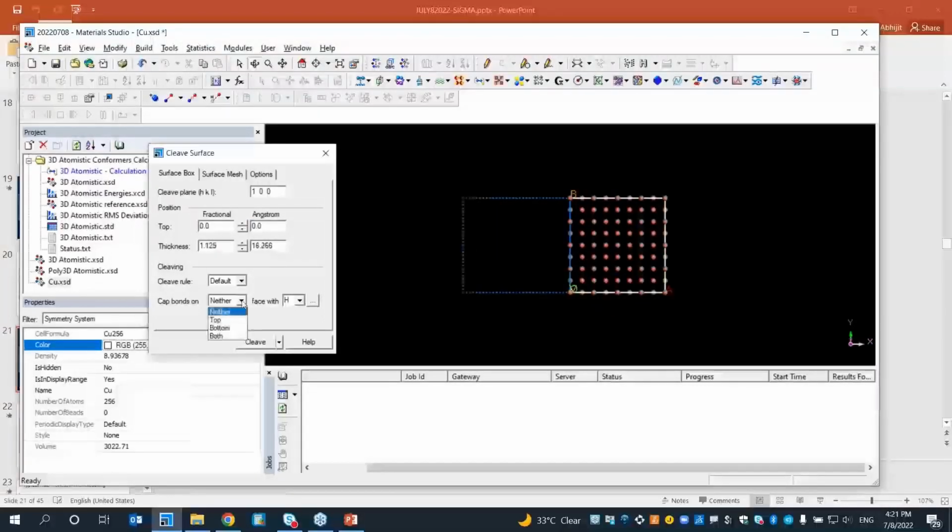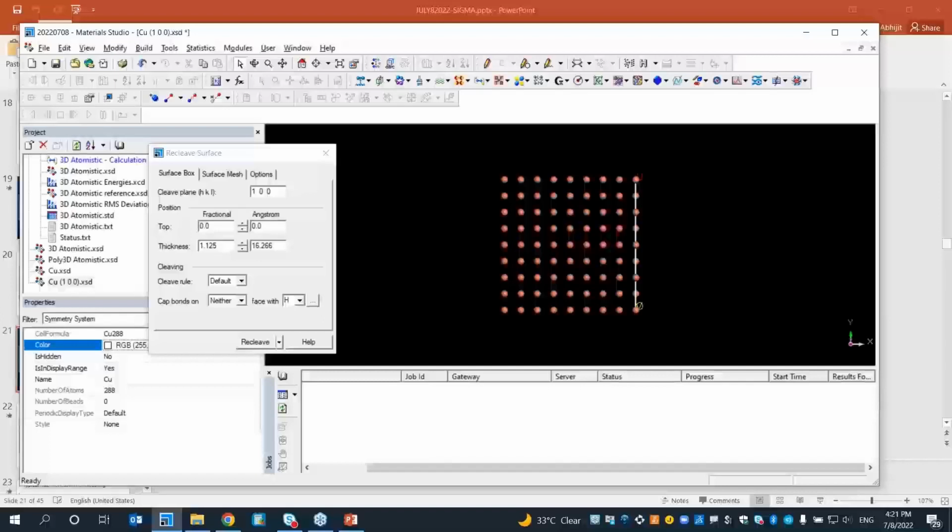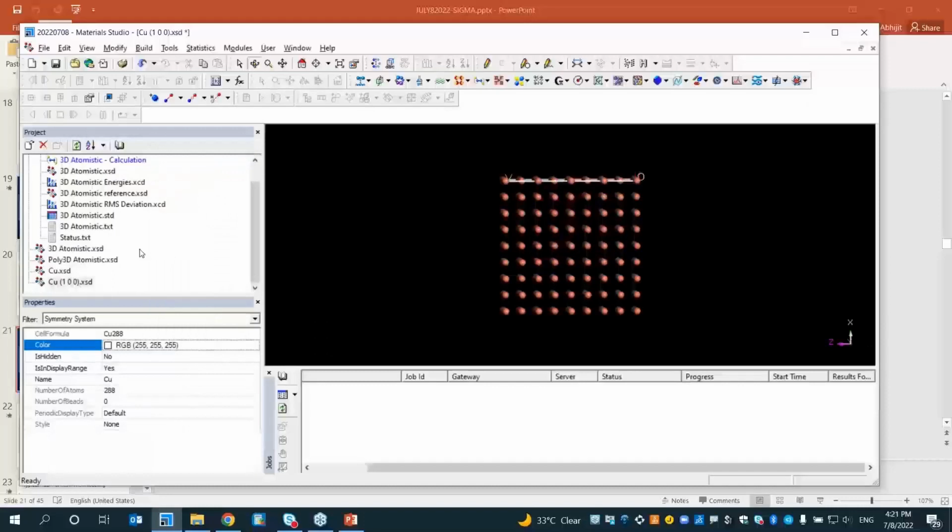This is a 100 copper surface, which is bigger with a couple of layers. And then you want to add this molecule over it. This is 2-dimensional, so we will make it 3-dimensional by adding vacuum over it. The rule of thumb is that the vacuum over it will be at least twice. So I think this one was 14 angstrom. I will just put 30 angstrom over it. So I see that this is my periodic structure.